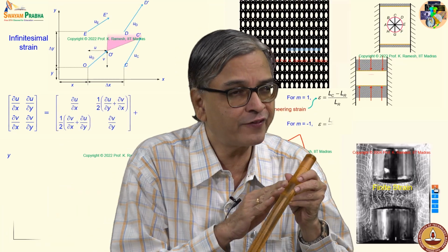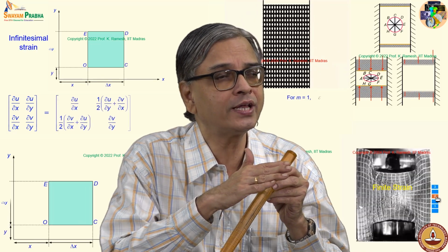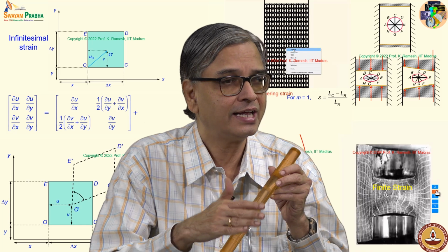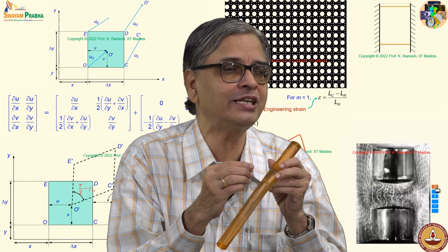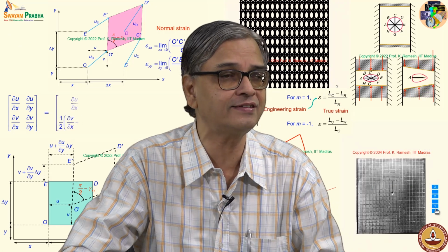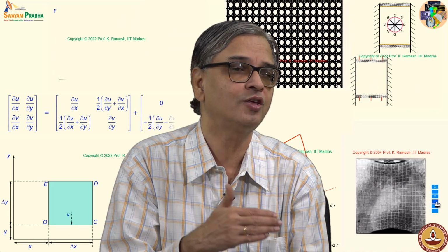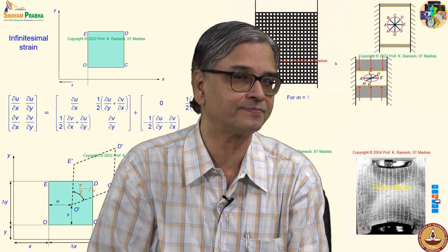The strain is faithfully transmitted to the coating. Because of the strain, the coating will get deformed, and because the coating is birefringent, all the concepts that we discussed in the case of stress analysis, you can have a parallel one. Like you have a stress optic law, you can also have a strain optic law.